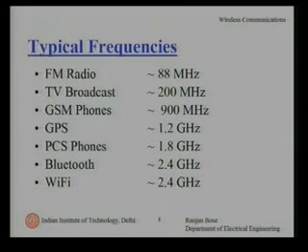802.11b, works at 2.4 gigahertz. 2.4 gigahertz has been a favorite band recently because it is a free band. It is also known as the ISM band. It is given to the medical industry, to institutions, to scientific establishments to experiment with, and a lot of useful appliances have come out on this frequency band. We have a wireless lab here where most of the experiments have also been designed around 2.4 gigahertz, simply because we did not have to take any license. So, it is a license free band. Please note, I have put in the number 2.4. It does not mean that is the only frequency that it works at. It is a frequency band all the time.